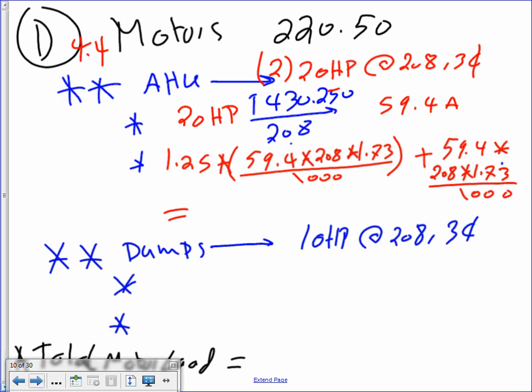When you do this step, your answer should be 48 kVA. The reason I did it twice is that I need to add 25% on the largest motor. There are two motors, and you pick the largest. There are also motors here, but those are 10 horsepower, and this is 20. Definitely, these are the largest. So at first I did the kVA for the first motor, added 25% on it, and then added it to the second one. That's using the largest motor.